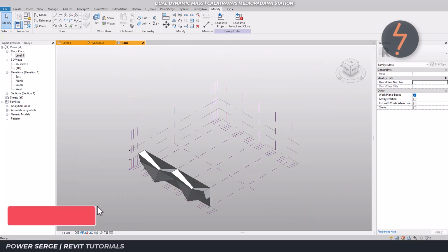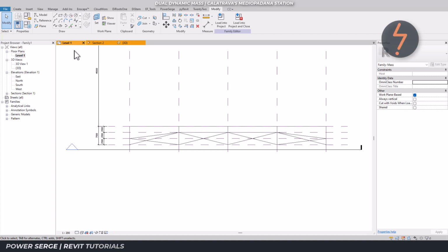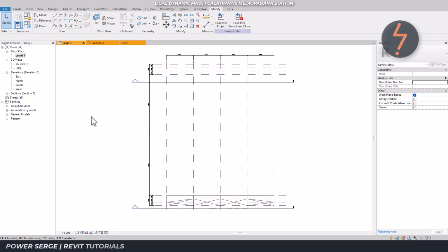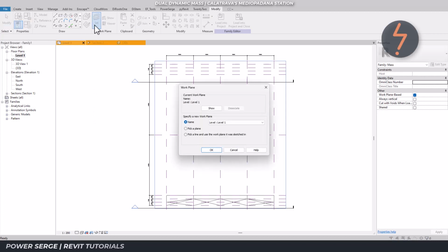Then repeat the steps you've just used in creating your W shape on the top side of the project, but this time we are going to invert it to create an M shape. Let's take this opportunity to revisit the steps. Start by selecting the work plane that will host the model line sketch.